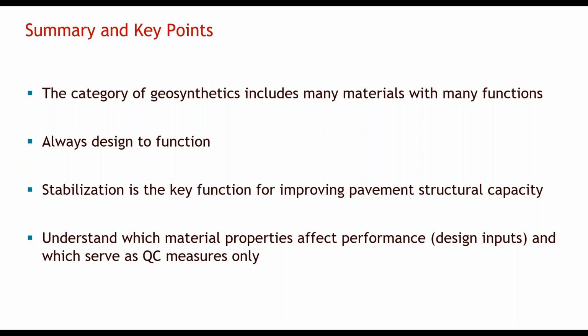Stabilization is the key function for improving pavement structural capacity. It's important to understand which material properties affect performance, and these will be design inputs to the design method that you're using, and which material properties serve as QC, or quality control, measures only. For instance, tensile strength.